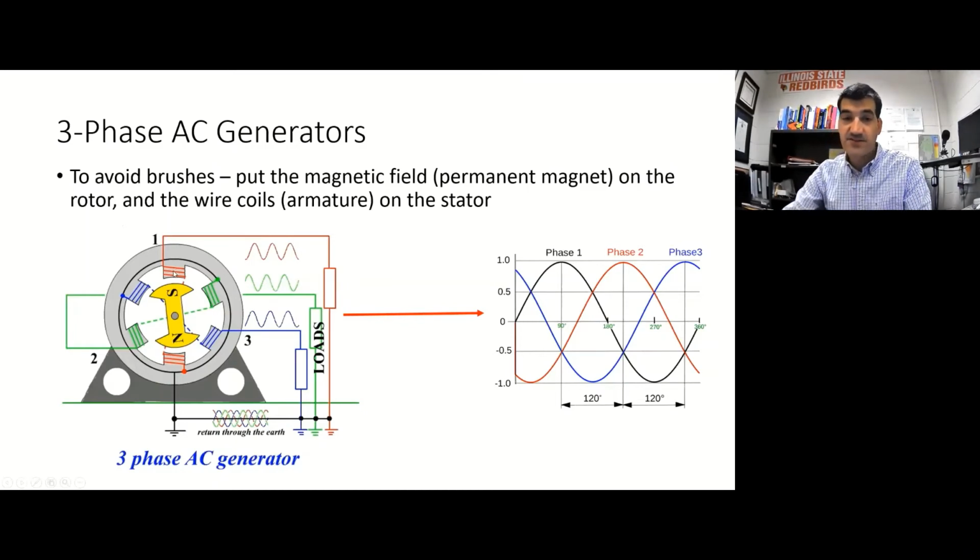All right, so this is relative motion. You don't have to have the armature rotating to get relative motion. You can get relative motion just by causing the magnetic field to rotate. All right, so I could get the exact same output as I had before. I can get my three-phase output over here with this machine, putting the field on the rotor and the armature on the stator.